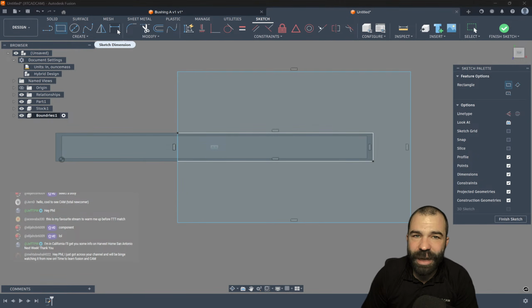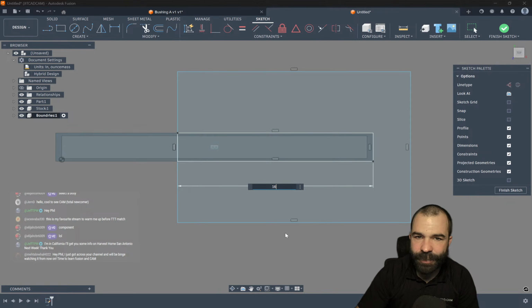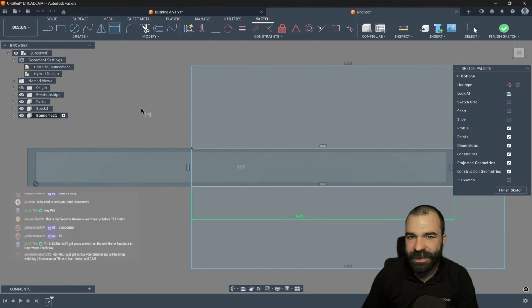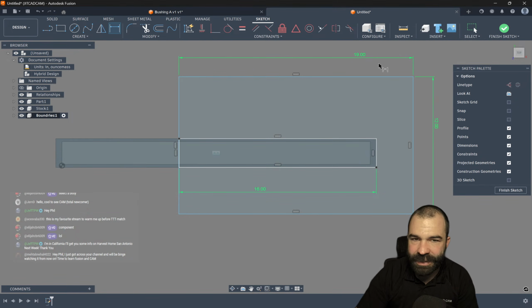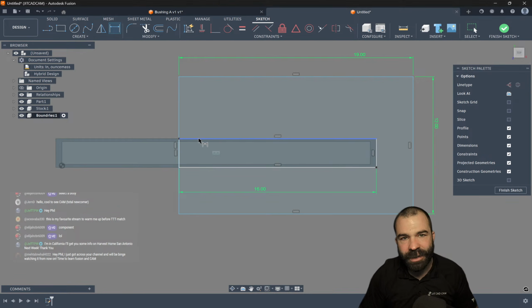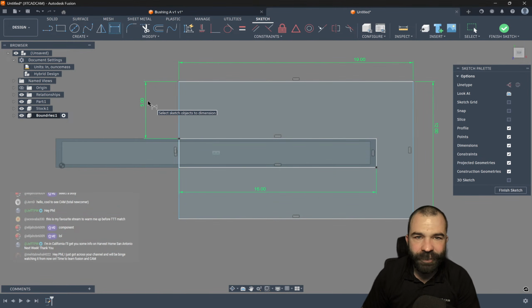Now, if you know your travel limits, this is where we could, of course, add a dimension. Maybe we're only going to make it about 16 inches. As you can see, I could plug in 16 inches. If you wanted to start going around and being fancy, 12 here, maybe this is going to be 19. And then with that, we need a distance from here just because, let's say it's 5. We're really just starting to work towards fully constraining that sketch. It's not a big deal, right?